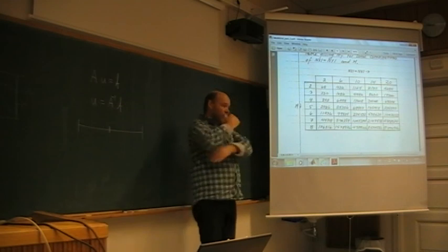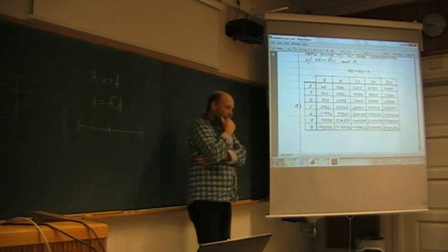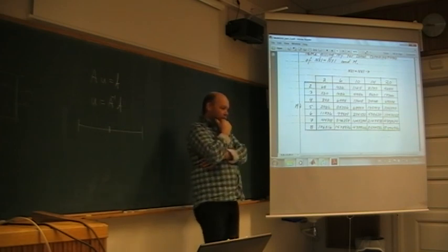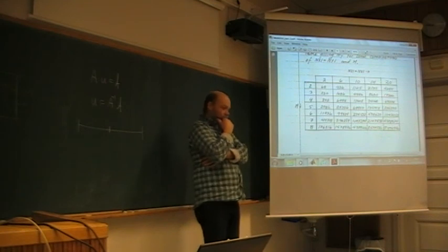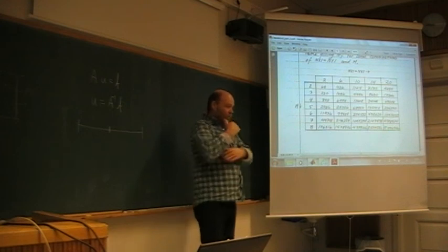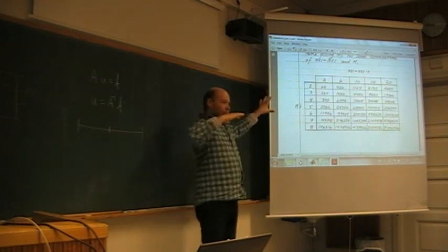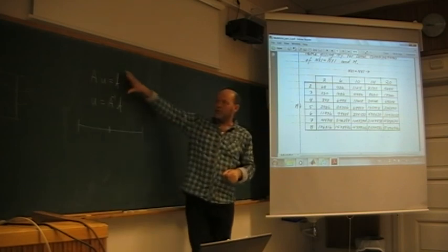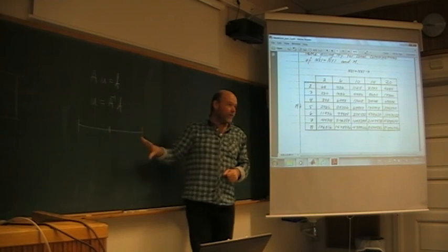I won't say it's illegal to take the entire Navier-Stokes and use multigrid on it. Could you even? That's non-linear. Could you even try? Yeah, you can do it. Then, of course, you can't use the residual equation. Then you will have to solve the original equation on every level.